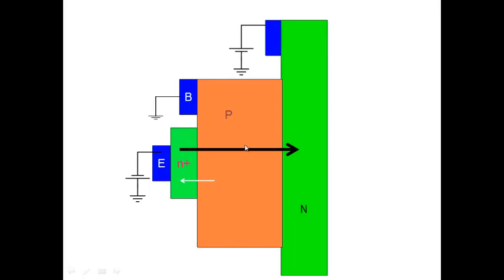So because you have fused them together and you have kept P small, the P thickness is small, whatever electrons you inject here go all the way to the N region. The whole current, of course, remains the same. The whole current is going into N plus, so nothing really happens to the whole current here. And therefore, you get something very interesting: when you fuse them together like this, although this junction, N and P, is reverse biased, a very large current starts to flow through a reverse bias junction. A very large current, and the origin of the current is actually injected from here.